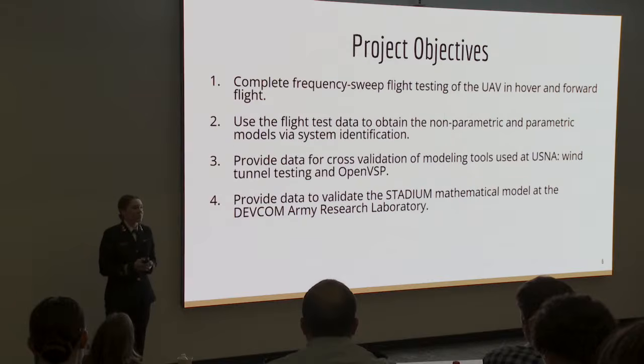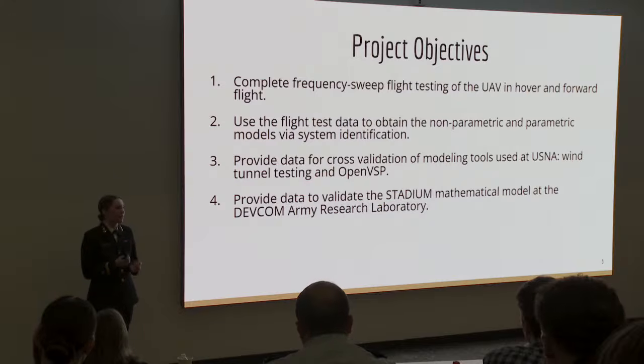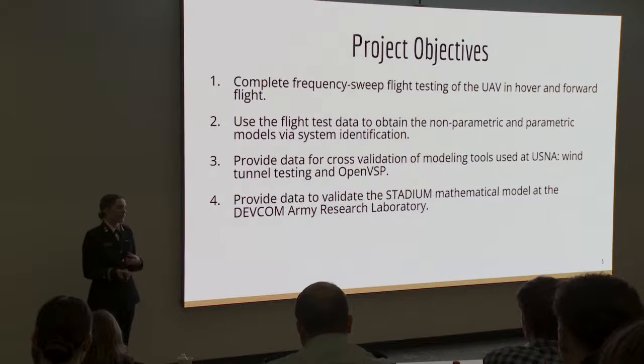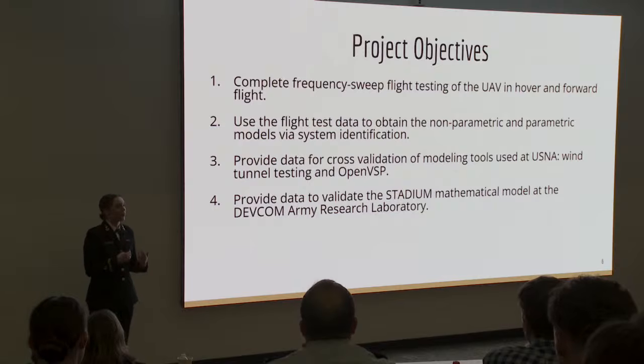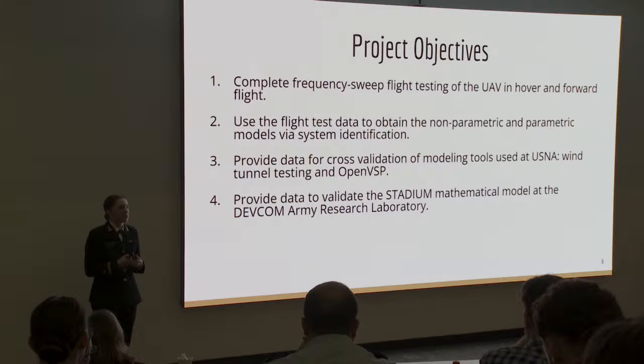And that was the main purpose and goals of this project. So we wanted to complete the flight testing of the UAV in both hover and forward flight, and from that obtain non-parametric and parametric system identification. Once we had those results, they would provide data to validate various modeling softwares, both capabilities we use at USNA, such as our wind tunnel and OpenVSP, as well as Stadium, which is a mathematical simulation modeling currently being developed at the Army Research Laboratory.